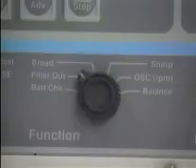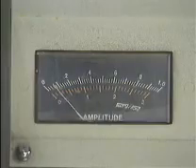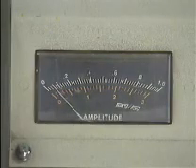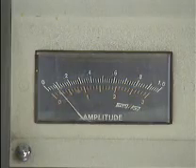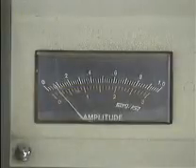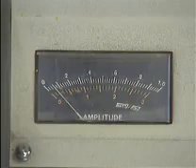One way to examine vibration is to look at the amplitude of a vibration over essentially the entire frequency band. If a machine's overall level of any of a vibration's characteristics stays relatively constant at an acceptable level over the course of several routine measurements, then the machine is probably in good condition.